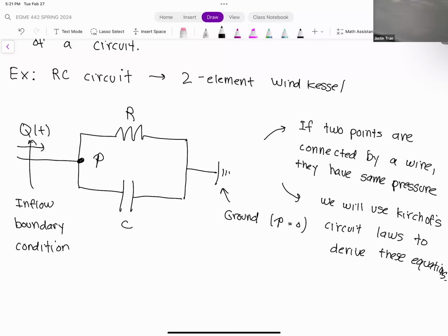Because your models aren't fully connected, I think you're going to have more caps. The cap is basically where the software takes the ends of your vessel and closes them off. If a vessel is mostly branching off but sticking out a little bit, it's going to create another cap. So I would delete all the models and make a single one. I think for yours you'll have extra caps, because your vessels aren't fully connected. So I have to create more paths. Exactly.